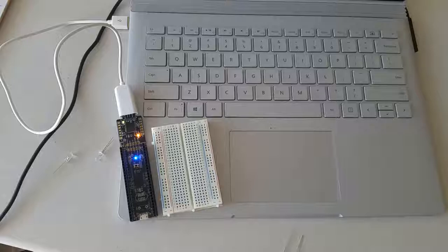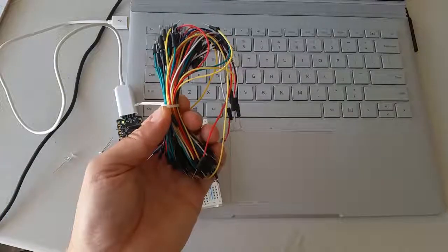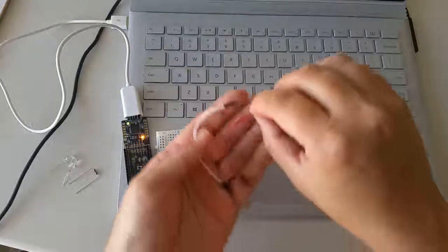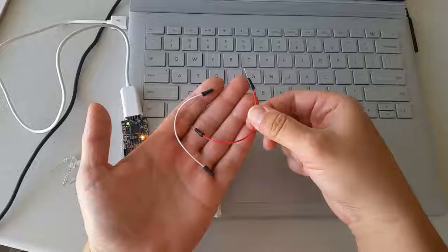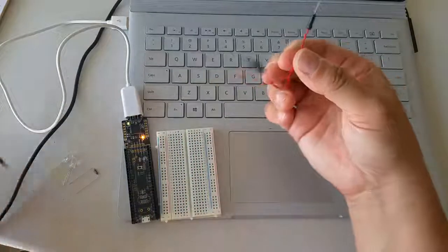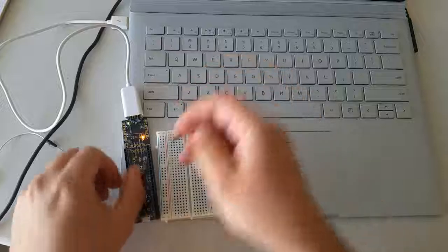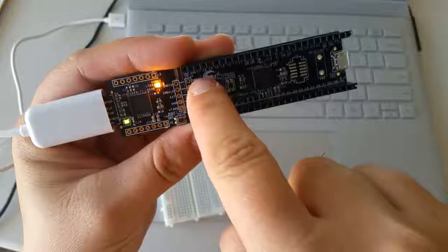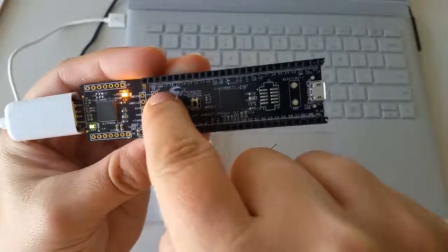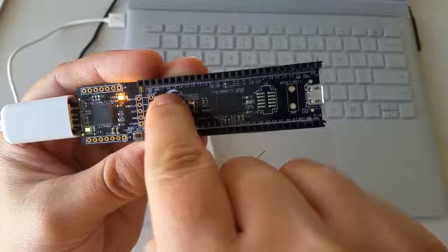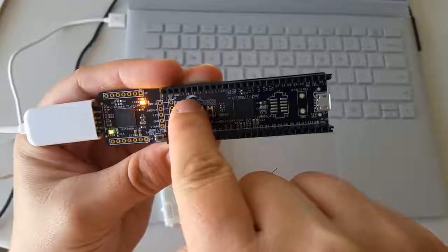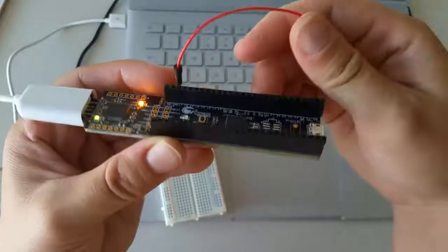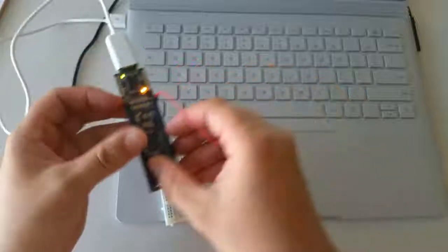Let's build this circuit. Find your pack of male-to-male jumper wires and cut off this zip tie. Take 2 wires from the bundle of wires and take one of those wires and connect it to the pin on your PSoC that is labeled 1.7. You can see the labels up here at the top, and if you look very carefully, you'll see that the 3rd pin from the left on the top here is labeled 1.7. Plug in one end of your jumper wire to that pin.